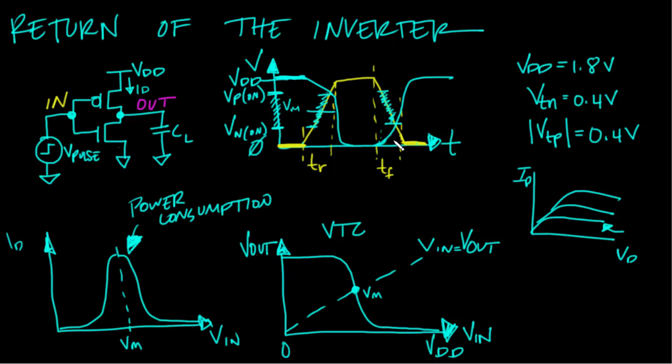It almost looks like indecision is happening here, right? And in the digital world, lingering between the high and low values comes at a cost. It comes at a power cost, but it also comes at a time cost. So if this input pulse right here had been sharp and clean, something like this, had gone straight up, then what would happen is the inverter would have come straight down like this. Right? And so what you end up with is you have this huge delay between basically a decision. You have some amount of time between when the device actually has a valid output. And that's not something we want either. So not only do we have increased power consumption, but we also have increased delay in this situation. So this is not good, and this is not something that we want. So those are some of the impacts of a non-ideal input.